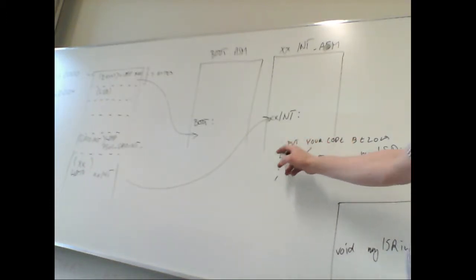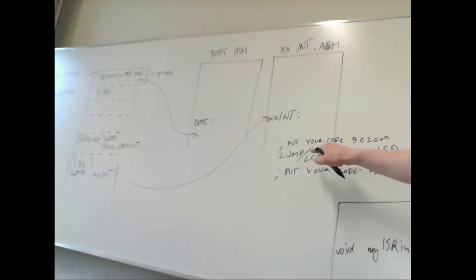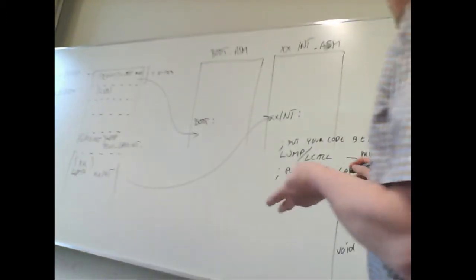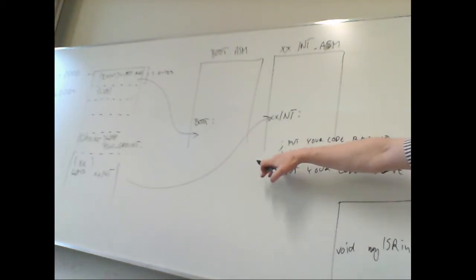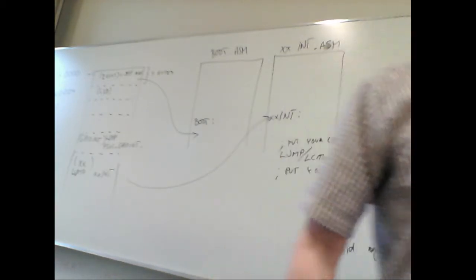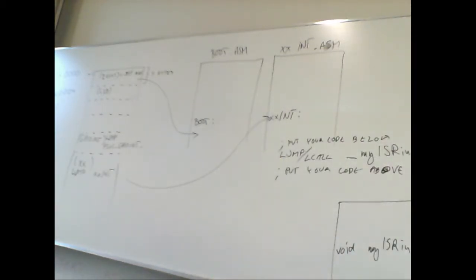The difference between long jump and long call is that if it's a long call, then this routine here is a normal function, nothing fancy about it. However, you can also do slightly faster code, not much, by not returning here at all, but doing a return from interrupt in here instead of return. I should probably use another color here.